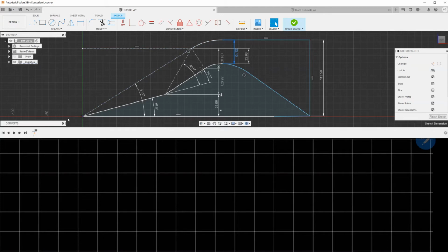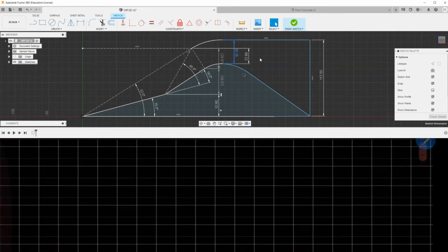The main goal of calculation of the drag on the diffuser is the drag on this central body, which is composed of three sections. Section 1 after the first shock wave, section 2 after the second shock wave, and section 3 after the normal shock wave. Also, there is a small piece here, which is the pressure close to the combustion chamber pressure, and I will separate this into another part contribution.